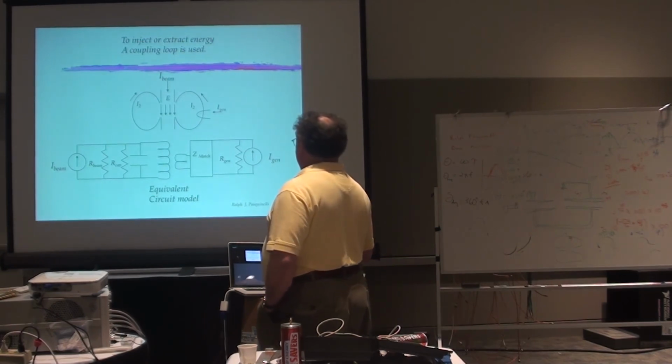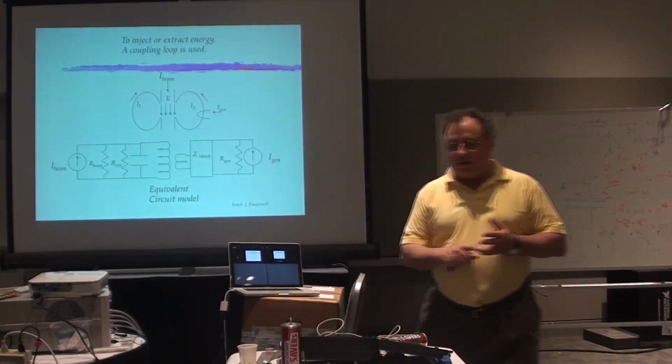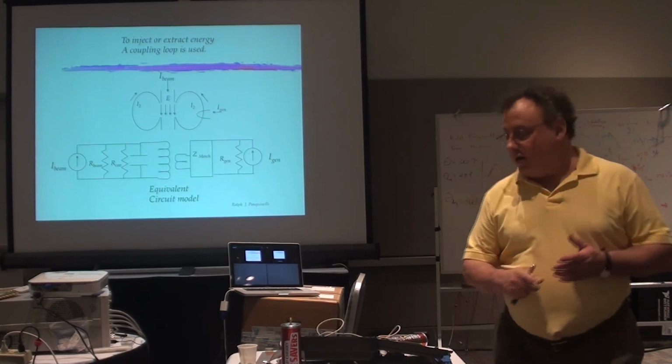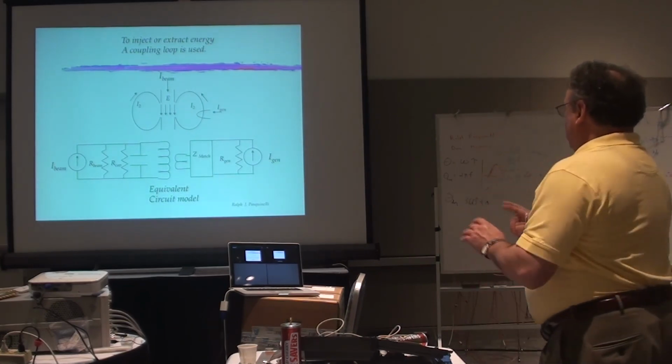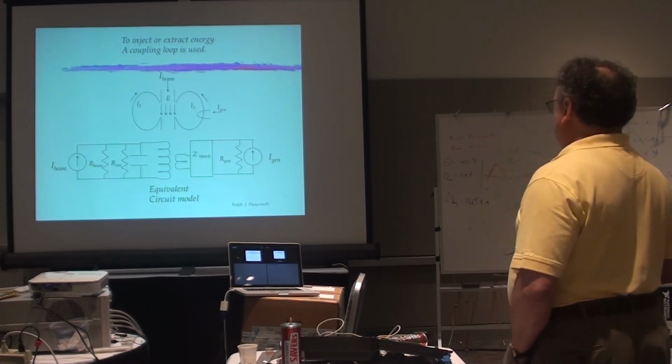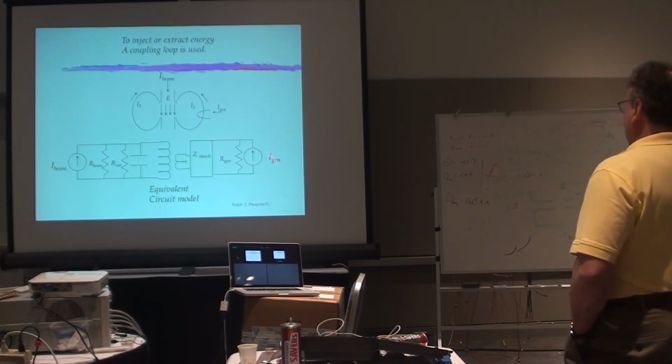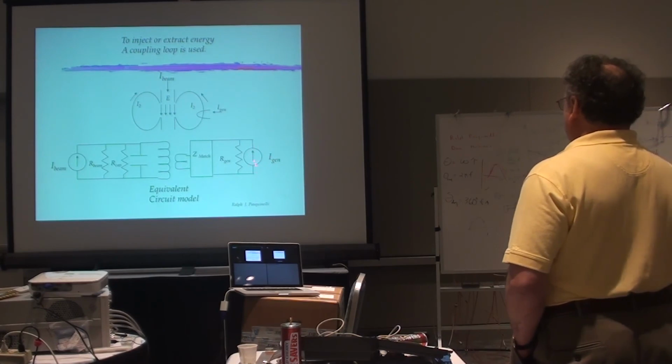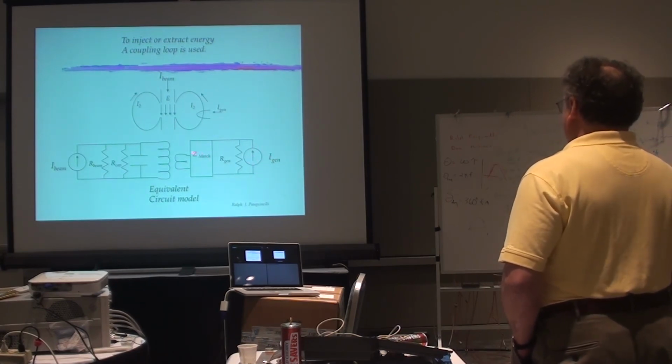We know about the cavity, we know about the power sources, we know about matching, we know pretty much everything we want to know about trying to make a system. And so now we just put it in some schematic function, where I've got a generator that generates my power, but we know it's not the right impedance, so I need some kind of a matching network to go into the equivalent model of the cavity.